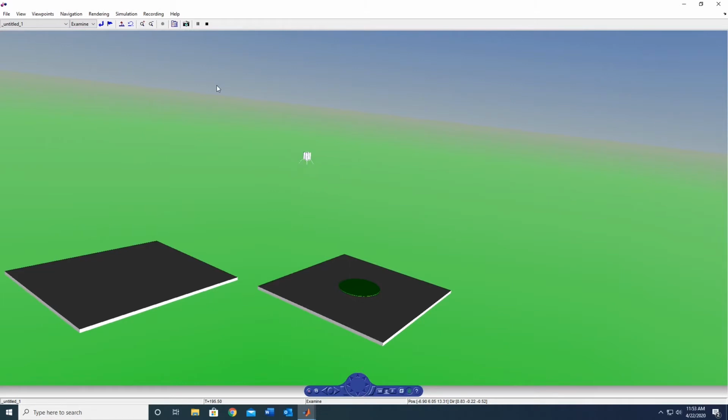The way I'm doing this is I'm feeding in the inputs from this joystick into a set of integrators, and those integrators add up the inputs that I give into the controls set point. So if I just let go, the value that the system is being told to go to when I let go of the controls is actually the value that the software latches onto and stabilizes.